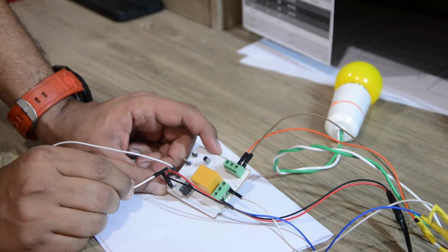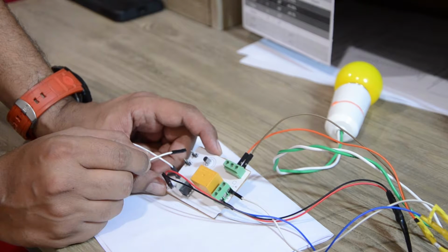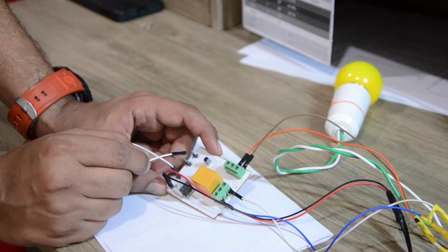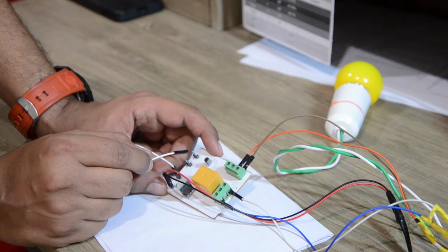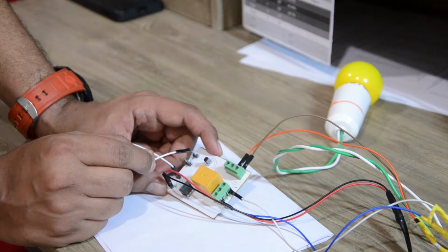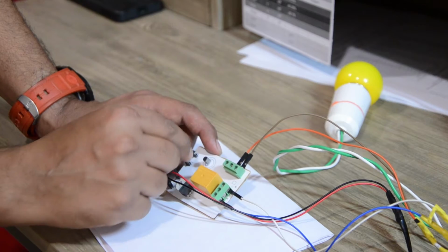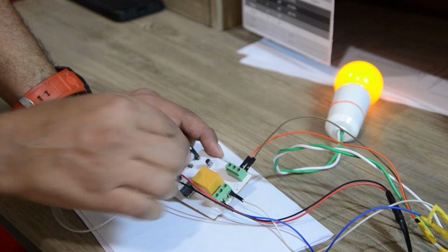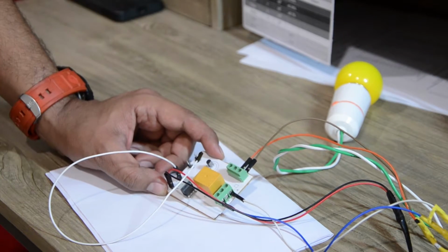So I'm connecting the 5-volt output of the relay board to the input of the relay board, just to simulate a scenario where I'm getting a logic high from the sensors. It might be a proximity sensor which has detected something in its proximity, or a motion detector sensor which has detected motion. It might give a logic 1 or a +5 volts output to the relay board, which becomes its input, and when that input comes, our appliance gets switched on. When I remove it, which is like being 0 volts or a logic 0, the appliance gets switched off.